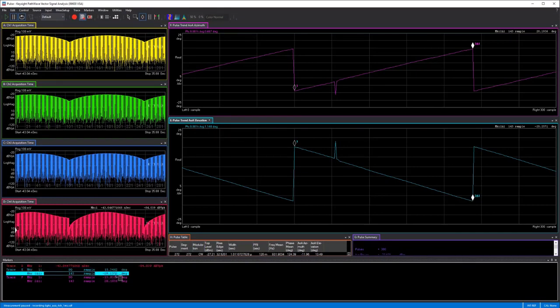And this corroborates what we expected, because based on our 4-channel UXG vector signal generator scenario that we created with our multi-emitter scenario generation tool, or MESG, we created a platform that is changing in azimuth from negative degrees to positive degrees. So it's coming from left to right. And the scenario we created is actually minus 15 degrees to plus 15 degrees. Secondly, in terms of elevation, it's going from a positive elevation to a negative elevation in terms of degrees. So it's moving down from looking up to moving down.